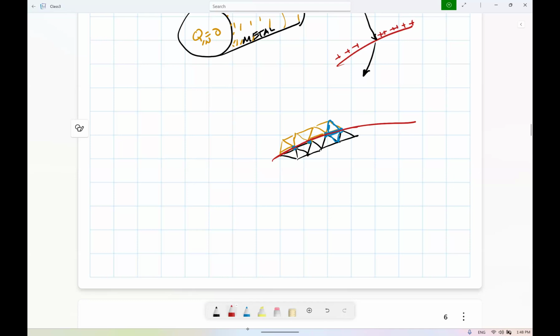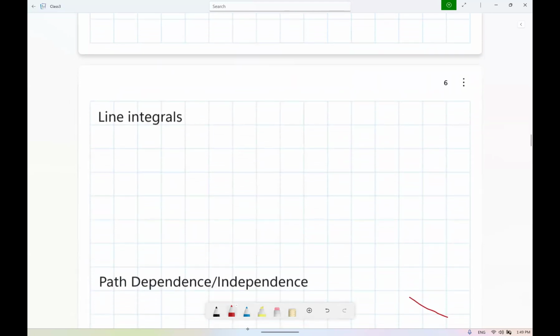Sometimes when we need finer tools, we need to look into the fields, details on something, we just put a boundary that is continuity, but just to make the meshing more efficient. To make the meshing more efficient, we could just put a boundary that doesn't represent any change of materials. We need to put a boundary every time that the materials are changing. Yeah, because you need to define the physical properties, you need to establish where things change at those points. All right. Okay.